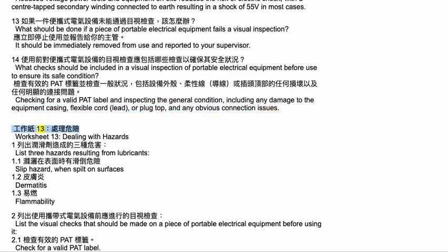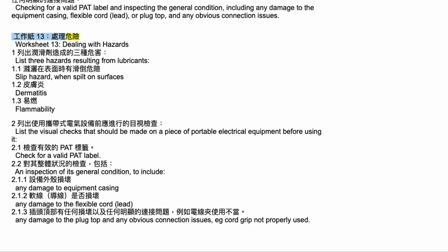Worksheet 13 Dealing with hazards. 1. List 3 hazards resulting from lubricants. 1.1 Slip hazard when spilled on surfaces. 1.2 Dermatitis. 1.3 Flammability.